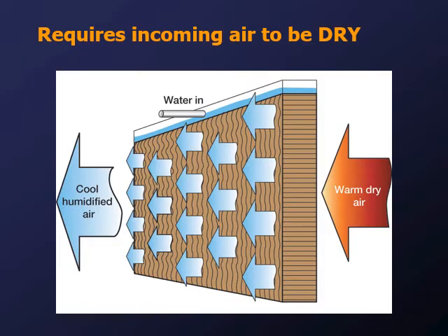This is just a picture showing a water reservoir that trickles down, keeping the cardboard wet. And then your outside warm, dry air comes in, picks up the moisture, and as the water is absorbed by the air, it cools the surface, which in turn cools the air coming in behind it.